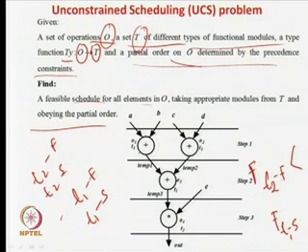So, that is a general rule of thumb we will take, and then we will go for the allocation procedure. You will know that these are the time steps, and each time step has some time units. So, if you say that this is, say, 25 nanoseconds, what does that mean? That means that these two additions operate in parallel, and they should be over much before 25 nanoseconds. If you take it as 10 nanoseconds, then you may be in a problem, because we say that step 1, step 2 or step 3 are of equivalent size.